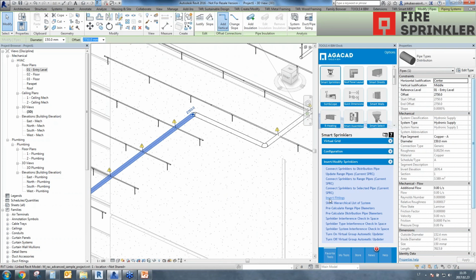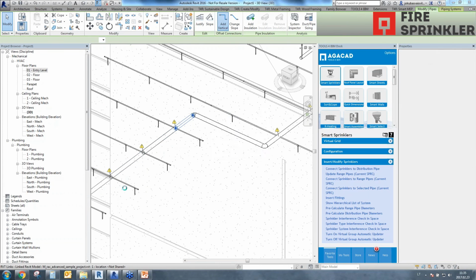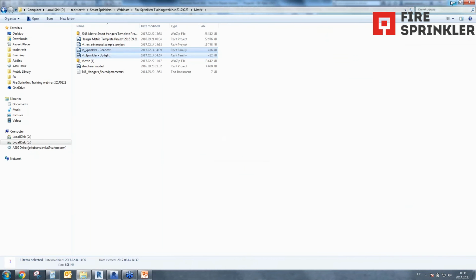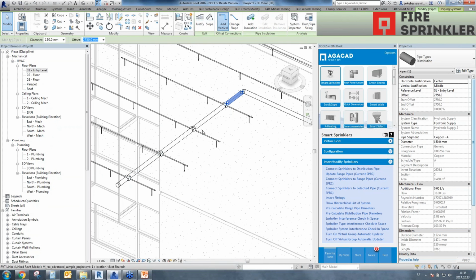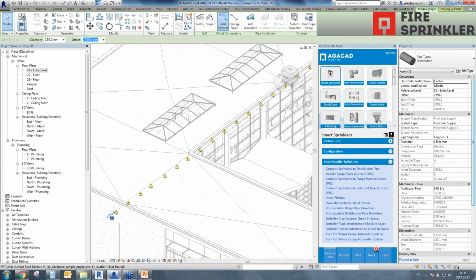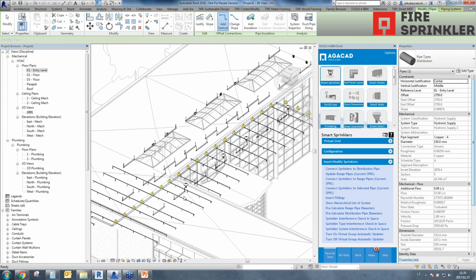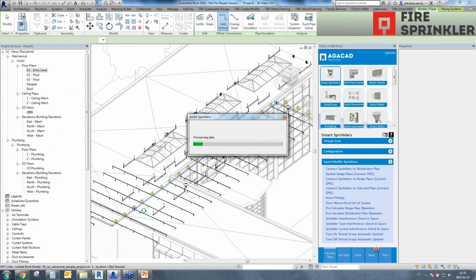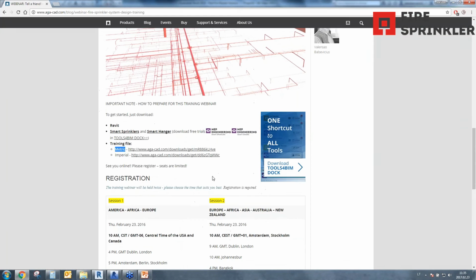So I can suggest you hit the insert fittings feature, and it will find all the intersections between pipes, and will insert fittings in those places. As you can see, it is splitting the pipe, and it is inserting the families. Again, here we have many more elements, and let's insert the fittings. Again, as you can see, it is trying to draw a new pipe everywhere. All the pipes will get new IDs because it's not possible to have the same ID for separated elements.